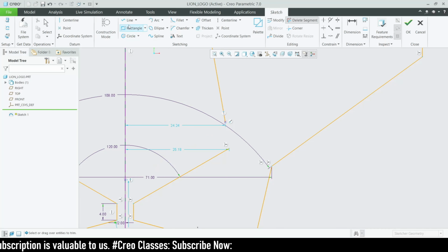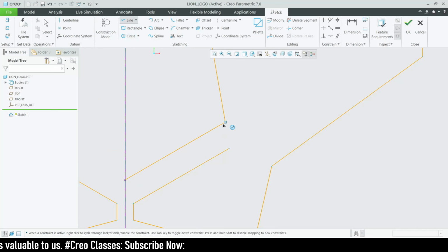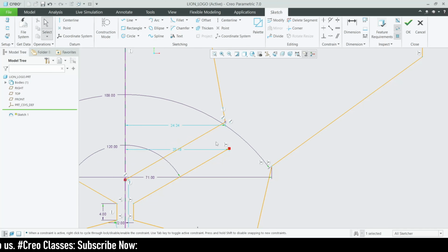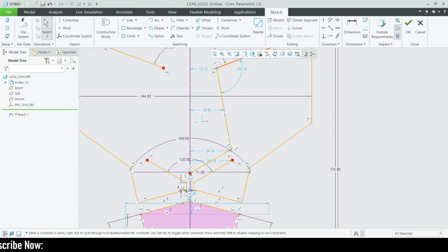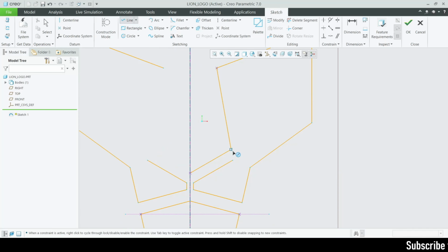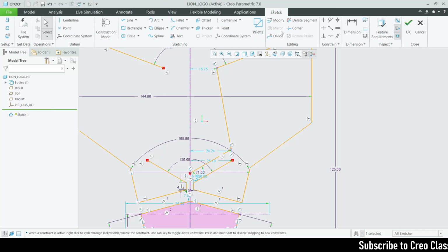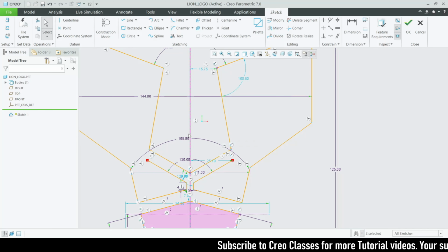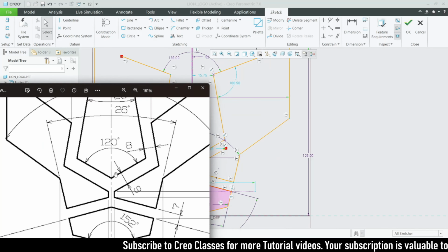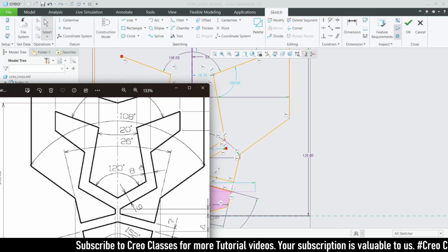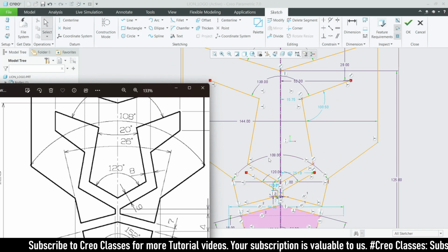Let's delete these lines and draw a line from this point to this point. Here I think this has got a single line feature or double line. So let's delete these two and draw a single line to this point, and select this line, control key, select this line, and mirror this towards the opposite side. And anyway, we got our feature. So we have created this nose feature also like this. Okay, this looks really good, right?